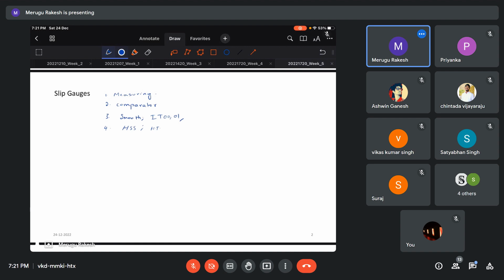Okay. What is the preparation process? Something related to smooth finishing only. So basically, we take the steel blocks, then cut them according to the sizes, then grind them as smooth as possible. Then the final finishing is with the lapping process.